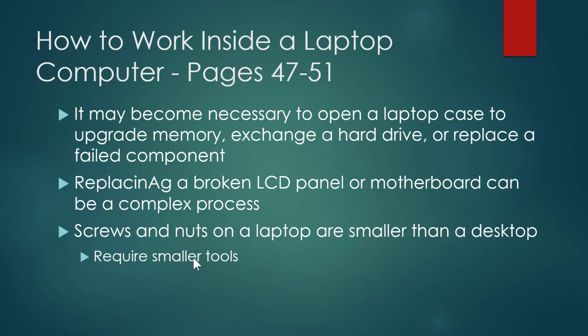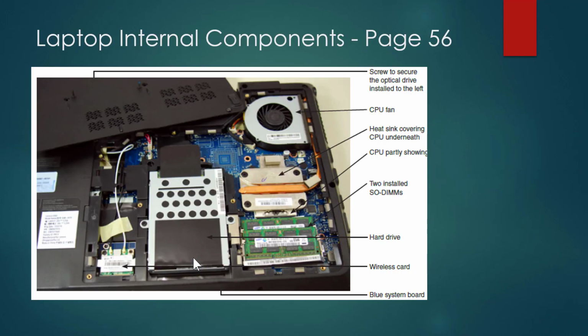Working inside of a laptop, if you have to open it up, such as to replace a broken LCD monitor or motherboard, is a very complex process. You could be looking at 25 or 30 screws, and you need to be very disciplined in your approach to disassembly of the computer. Screws and nuts on a laptop are smaller, and you're going to need more than a 6-in-1 screwdriver to work on that laptop. You're going to need some sort of laptop repair kit that has extra pieces, and it should also include tweezers and plastic scribes to be able to get inside the laptop easily.